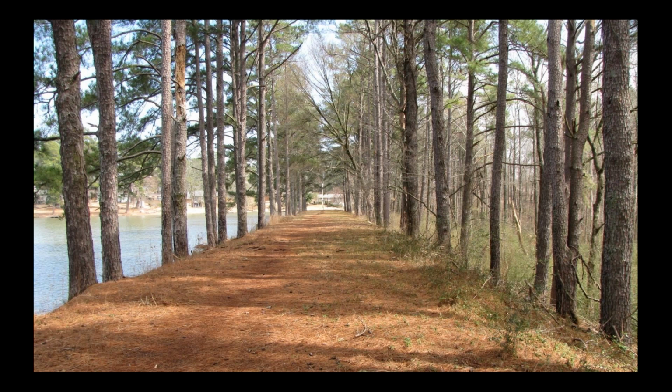And I'm looking at this one, and I'm pretty sure that whoever was building this dam or maintaining this dam deliberately planted these trees. It looks like they're pretty evenly spaced, and they're just on the outer edges and not on the downstream slope. So that's a real no-no. There should be no woody vegetation on the dam, especially at the crest of the dam. So if I was inspecting this, this would be a deficiency.